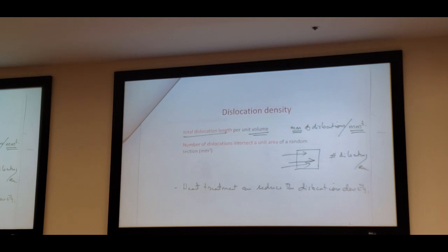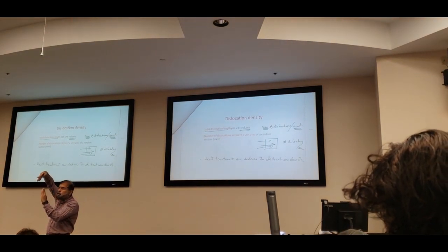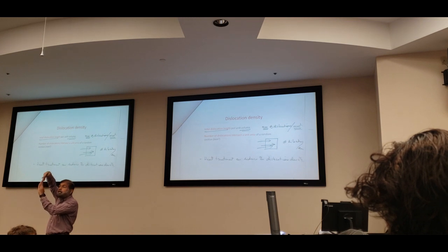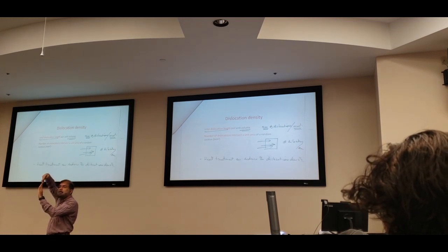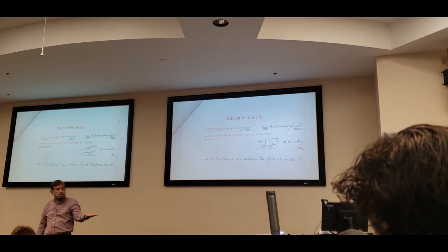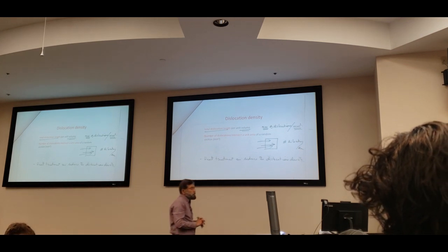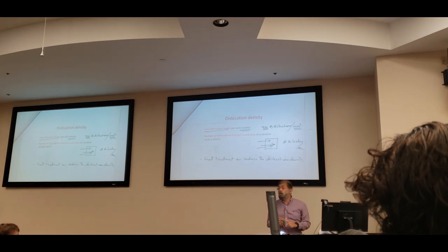What happens? You enable that dislocation to move so that it can recombine. Okay, don't worry about that recombine. I will show you how the dislocations recombine. Think about it. This is a half plane here, somewhere on top, and this is a half plane somewhere at the bottom. If they move like this, what happens? Annihilation happens. Agreed? Now it's a single complete plane. That's how the annihilation happens. And that's the reason why, as the temperature increases, the number of dislocations decreases, because of the easy movement of dislocations.